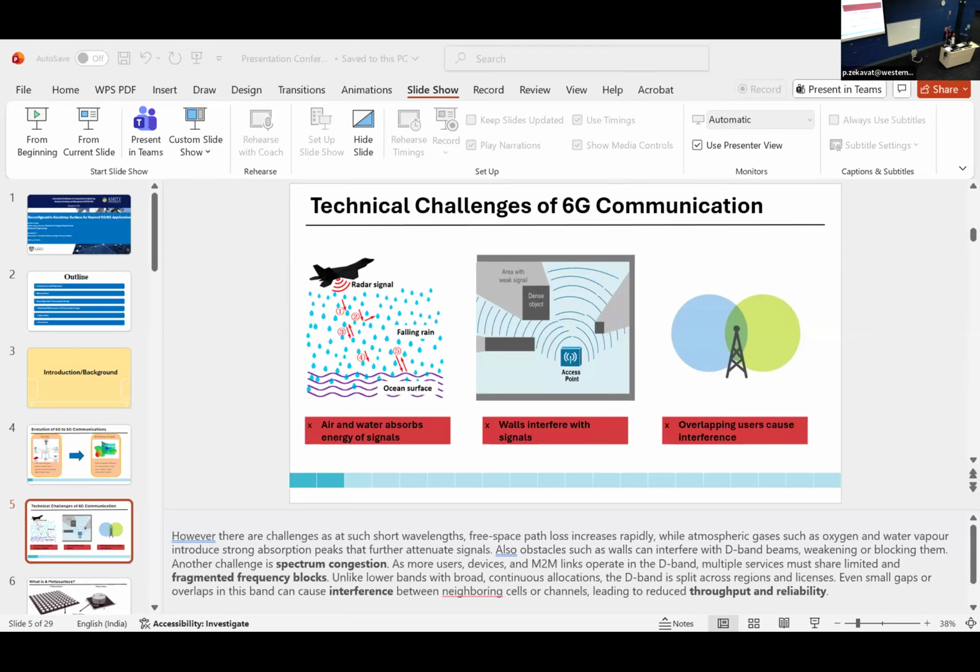However, I will state several limitations and assumptions, as the simulation assumed ideal conditions, neglecting fabrication tolerances and material losses, which may affect real-world performance. And then the diodes were modeled as perfect conductors, not reflecting the actual electrical behavior. And then additionally, edges and finite array effects were ignored due to the periodic boundary setup of being an infinite array.